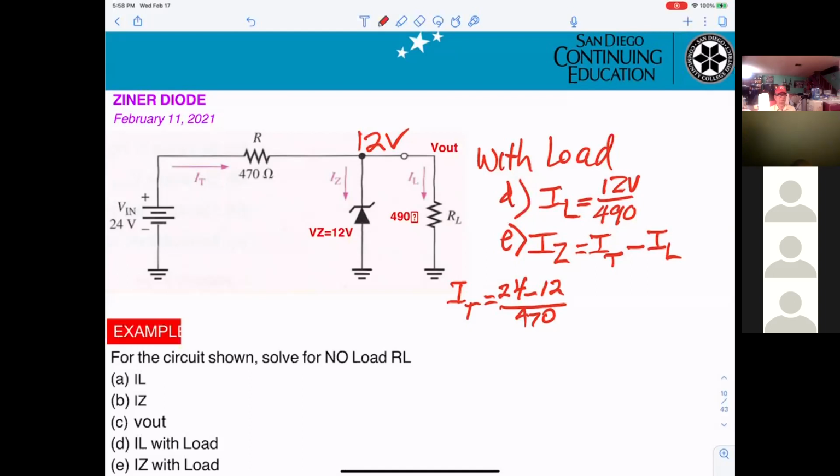You have no power supply there at all. It's just telling you the rating of that component. After that, that's how you calculate your circuit. It will only allow 12 volts past that diode, so V out will be 12, if V in is higher than 12 volts.